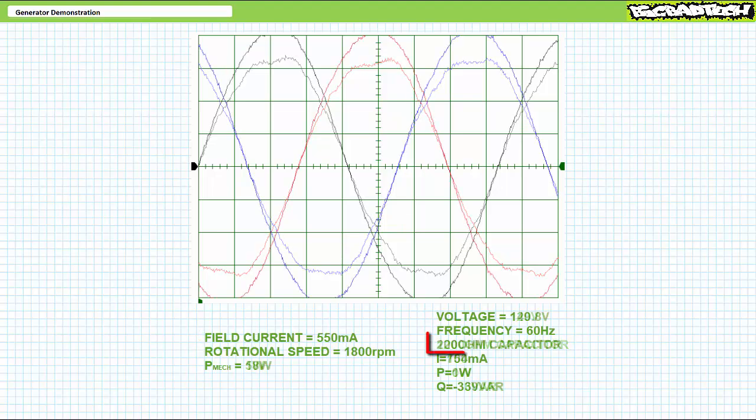Case in point, consider a second load profile consisting of 200 ohm primarily capacitive impedances. When subject to increased capacitive current draw, output voltage magnitude skyrockets all the way up to 149 volts. This is definitely not good. Each capacitive element draws roughly 750 milliamperes of current and supplies roughly negative 113 VARs of reactive power each for a total demand of roughly negative 339 VARs.